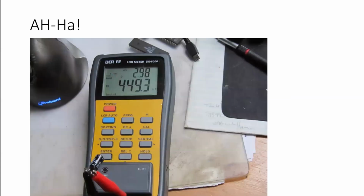So at this point, out come the big guns, and this is a proper LCR meter. Now this is money, but it will measure, as you can see, 450 nanofarads. Now, 450 nanofarads for a capacitor that is supposed to be 100 microfarads. 450 nanofarads is a 2,000th of what it should be. Right, that should read 100 microfarad. It's reading half a picofarad. It really is nothing, a 2,000th of the value.